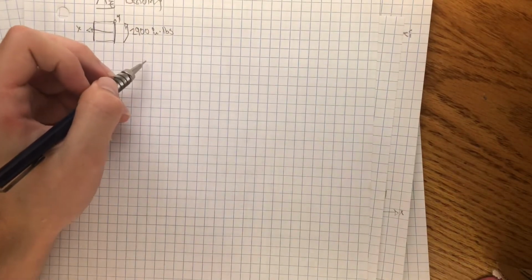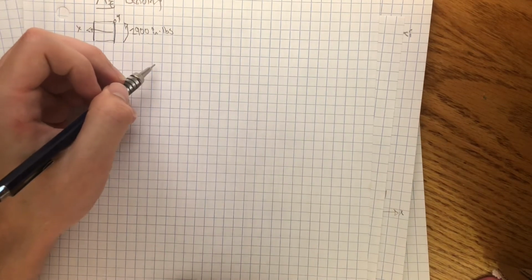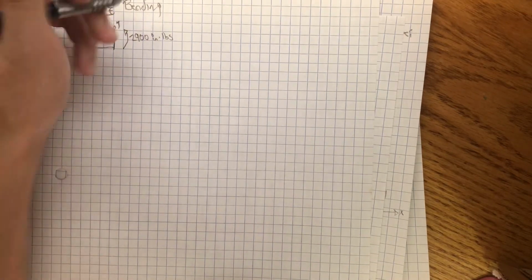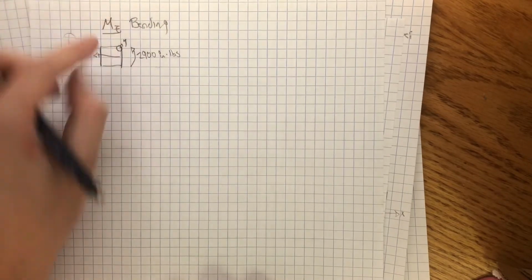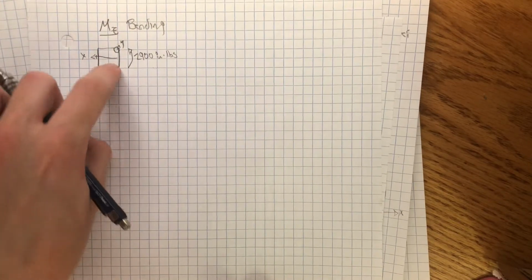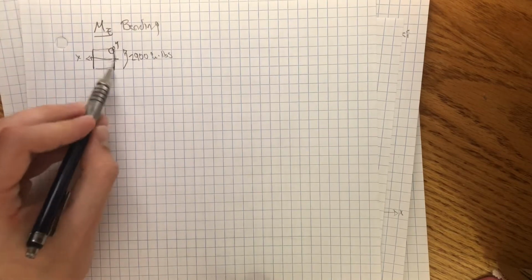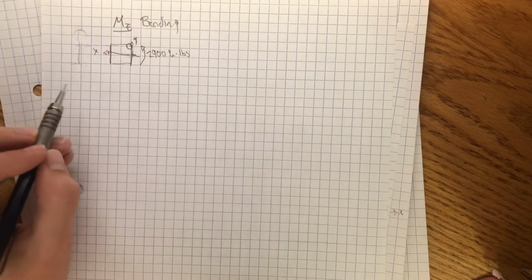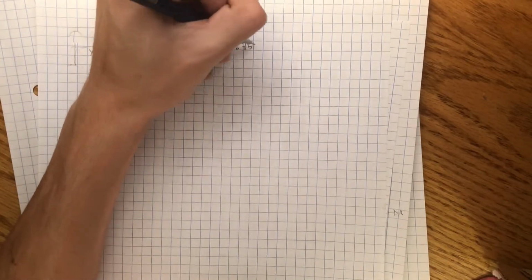And we know that the distance of our point of interest, which is up here because of this plane that we're looking at it from, is 0.75 inches away from that neutral axis right there, because this thickness overall is 1.5 inches. So that means that our y bar is equal to 0.75 inches.